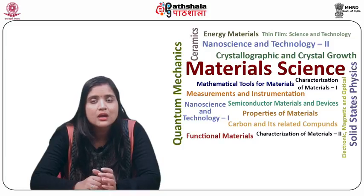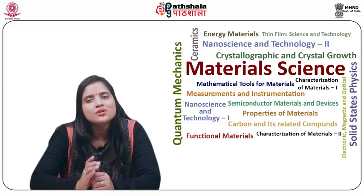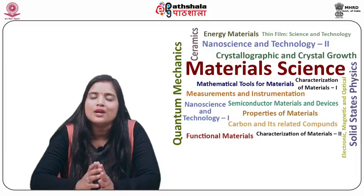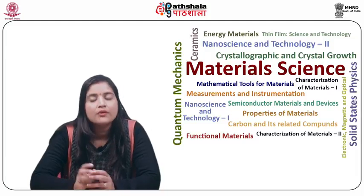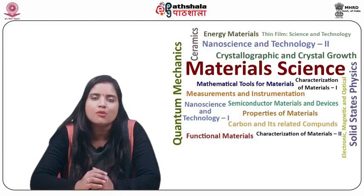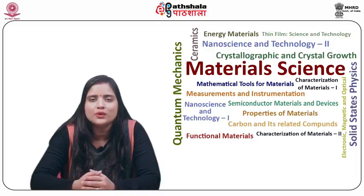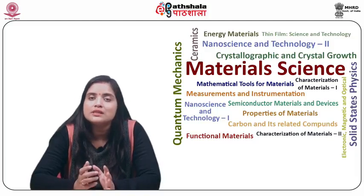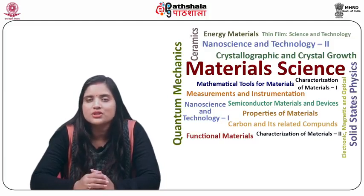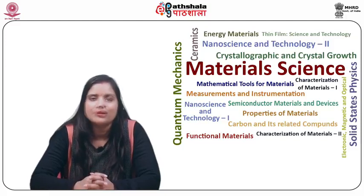In this technique, microscopic beads of Teflon are co-deposited, up to 20%, along with the electroless nickel. This coating is highly desirable for solving problems like sticking, galling, or dragging with moving parts or heated sealed surfaces. This can be a better alternative to liquid lubricants in some applications.